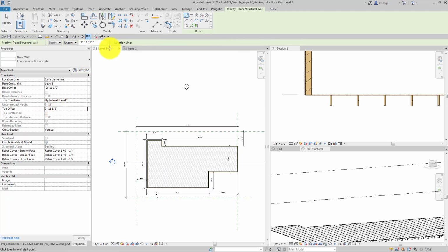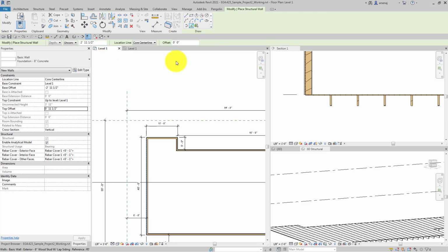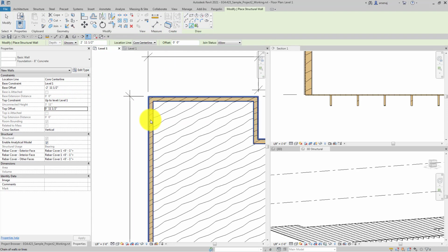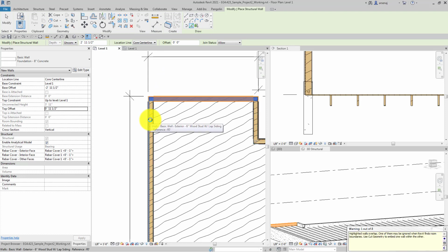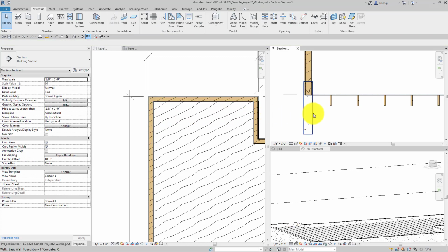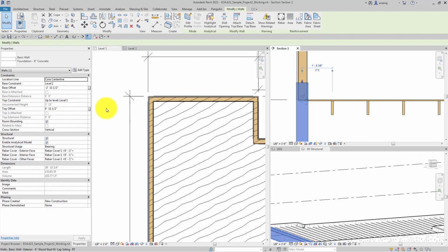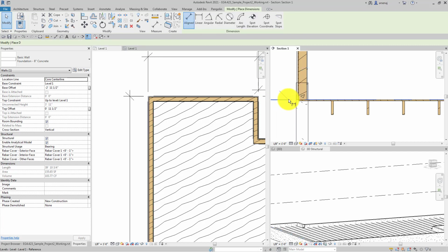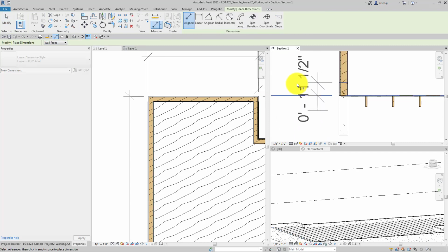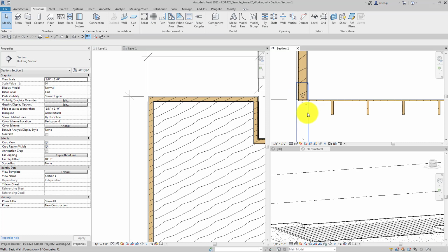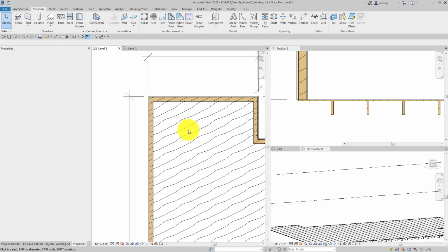And let's create this in our architectural view just so we can use these walls above to place this wall. So you can tab over the walls and then pick, and we can see where it placed the wall. In this case, we gave it a 11.5 top offset, and it actually went 11.5 inches above the level 1. So let's hit undo.